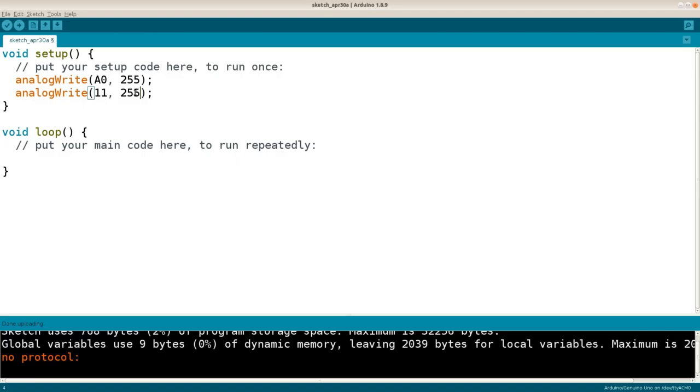And then we've got another method, that's analogReadResolution or analogWriteResolution. analogWriteResolution allows you to set the resolution, and analogReference allows you to set the analog reference, the high voltage, whether it is 3.3, 2.5 or 5 volts, depending on your design, and so on.